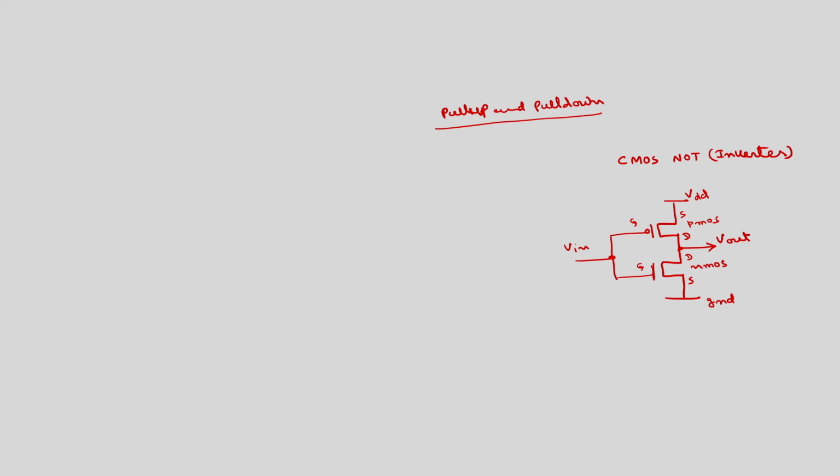So, now to explain the NAND and NOR operation, in the last lecture I have taken the ideal case where if a transistor is on, I have taken it as a short circuit, off, open circuit. But if I take the practical case, there will be some resistances. If I take this simple NMOS FET, it has source, drain, gate.